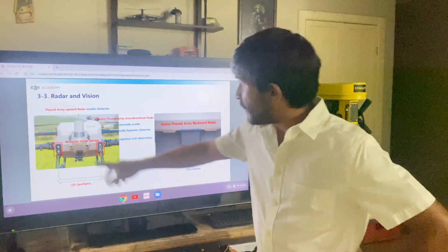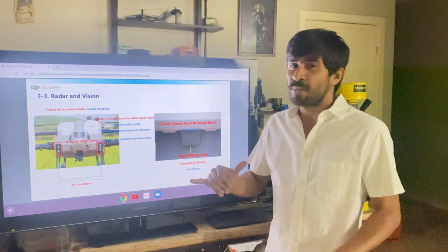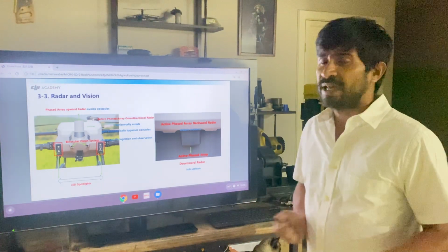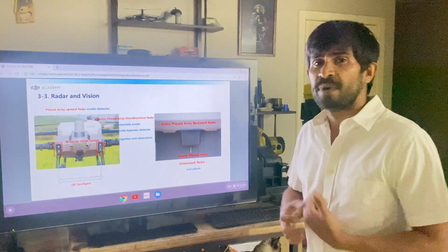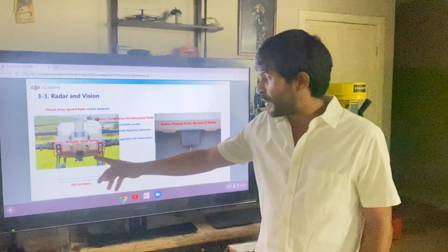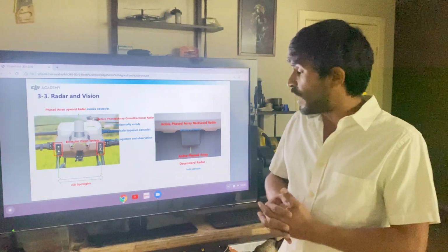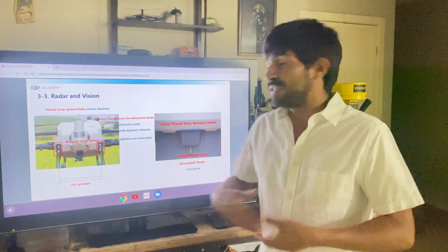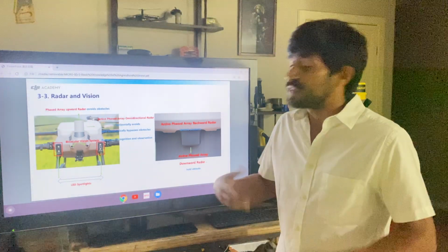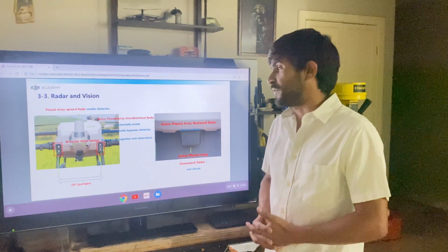This time you have this binocular vision system, which is two binocular cameras. They take pictures and calculate the differences between them to work out how far or close you are from an object, like an obstacle. They are very good when they work. You have to be careful to keep them clean. You have to clean them every some number of flights. Otherwise, if they get blurred, you don't get the advantages of auto obstacle bypassing, right?